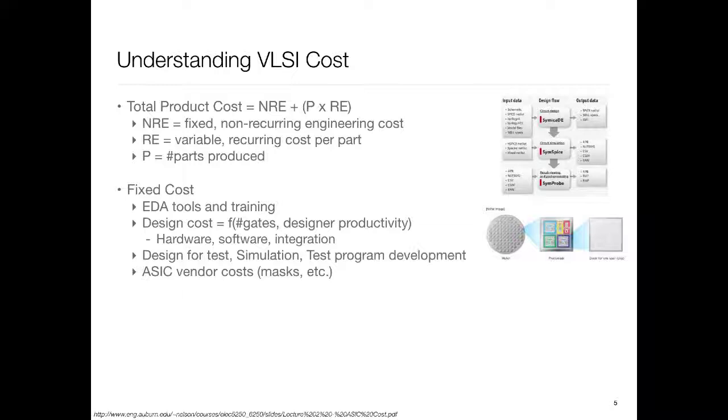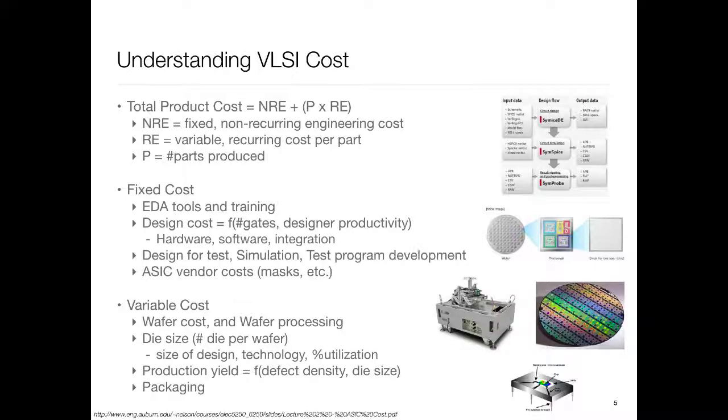Generally speaking, designing hardware is more costly for the same algorithm than writing the corresponding software. You also have to budget for testing. You have to get those masks made, and that non-recurring cost for something modestly complicated would be pretty huge. Then the variable cost is the cost of the silicon, of making it, and of testing it, and this is where simpler things have more advantage.